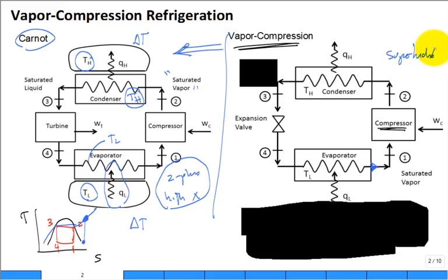Superheated. And that's a key concept. It's now superheated at state 2, which means for the first section of this heat exchanger, it's going to de-superheat the refrigerant, meaning that it's going to cool it. It's going to be rejecting heat, but as it rejects heat, it'll finally get to the point, maybe it's at this point, where it's now saturated vapor. And as I continue to cool and move along, it now condenses.